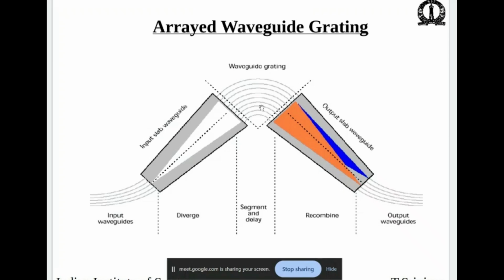The phase shift is dependent on the wavelength. This input section is for the mixing. It will say, for example, if light is coming from one of the ports, it will spread across all the delay lines, delay elements. So this is like antenna arrays. If someone has studied antennas, you can give progressive phase shift to each of, suppose there are n number of antennas, and each one is given a different phase shift. They will point in different directions.